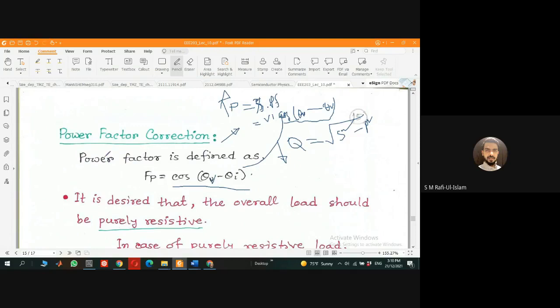So this is the case of why power factor is 1. In real life, we generally want to make this power factor as high as possible, close to 1. Because the cos theta value could go up to 1, if it's approaching 1, then we will be getting maximum real power. And maximum real power means the minimum reactive power, means the magnetic loss and some other stuff will be minimum, or the noise for some transmission would be minimum. So that's why the power factor is very important.